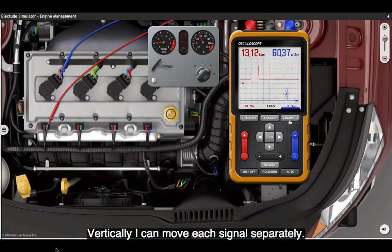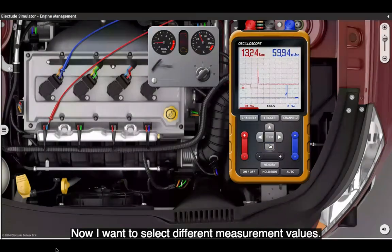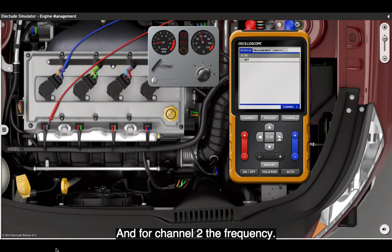Vertically, I can move each signal separately. Now I want to select different measurement values. For channel 1, I want to see the injection duration. And for channel 2, the frequency.